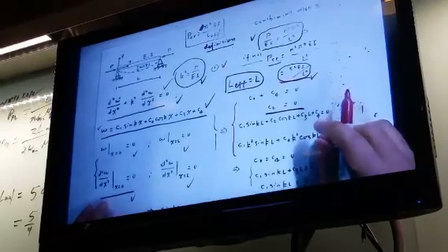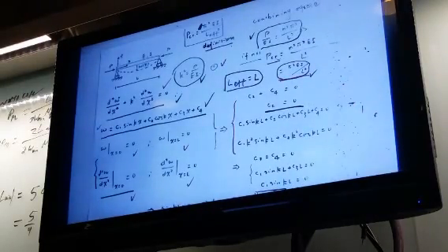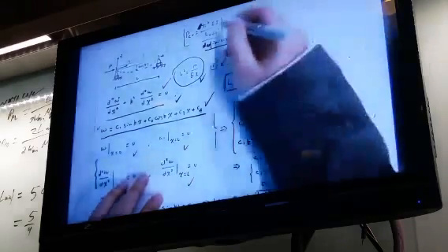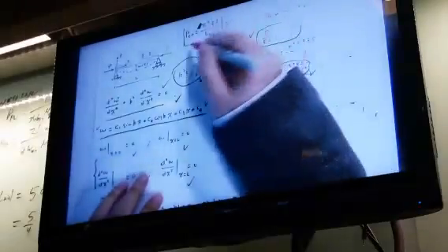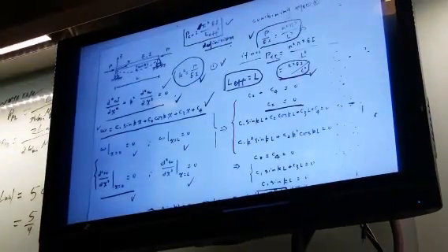And then you need to check. The question may be asking what is the effective length of this structure to have buckling. You need to check this result with this definition. This formula is the definition. No matter what the boundary condition is, the critical buckling loading is defined that way. But LEFF is unknown. You are trying to solve for it. When you finish your calculation this way, compare your results with that definition, and you can figure out what is LEFF.